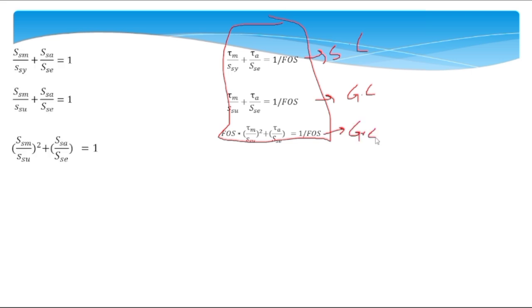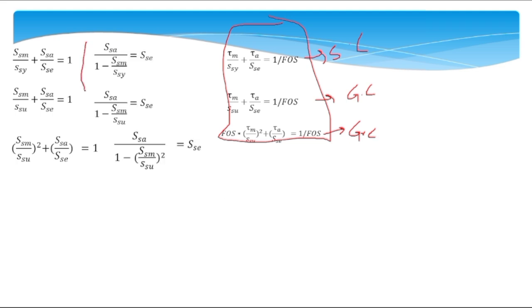Now from the previous slide we have obtained these equations as well. When we rearrange these equations for SSE, we will get these equations, and you know this is given by the Zimmerli data, and this is also given by the Zimmerli data. This is 35 and this is 55. Now if we find this and this, we can find this SSE for Soderberg, this SSE for Goodman, and this SSE for Gerber.